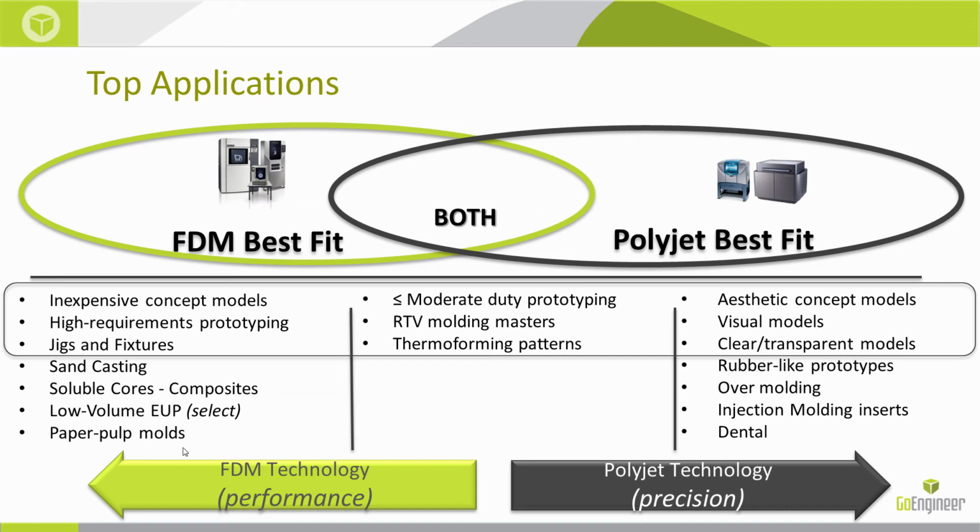You wanted to wrap it in a single wrap to improve the aesthetics, but also to maintain the integrity of that fiber matrix. We can print that pattern in the soluble material, do our wrap. These materials on the FDM side are robust enough to withstand the pressures and the temperatures of the carbon fiber curing process. And then we can dissolve the pattern out once it's cured.